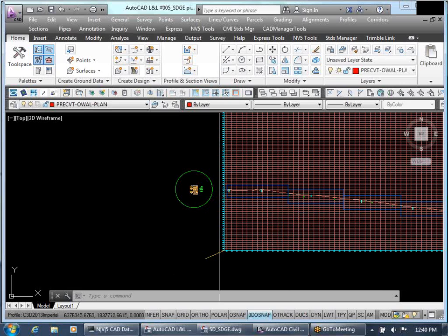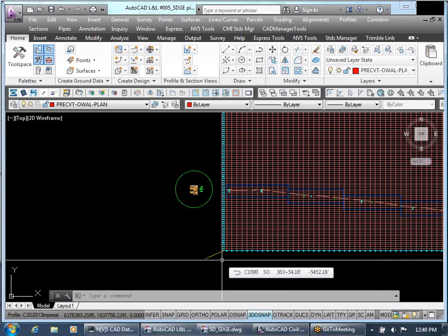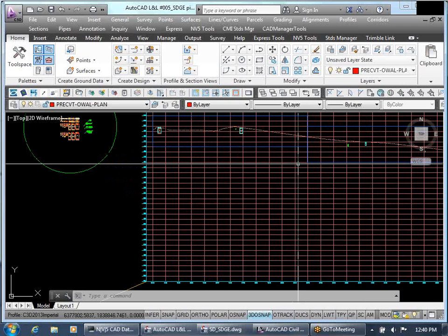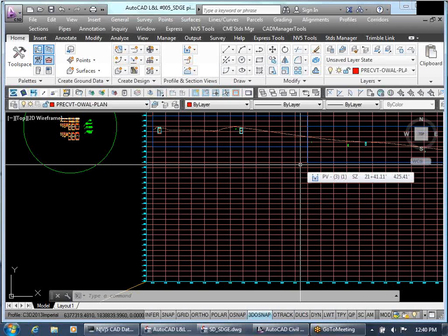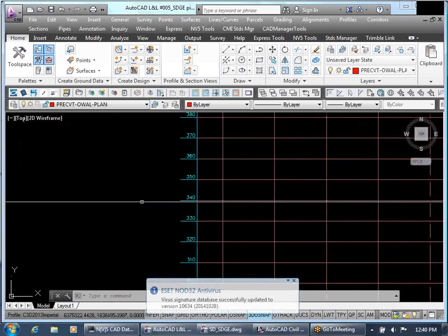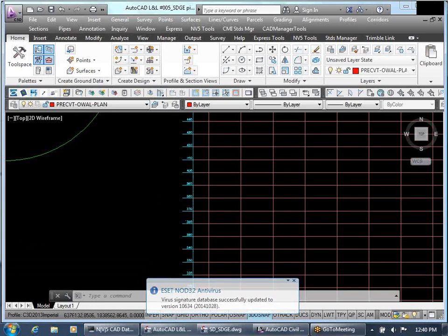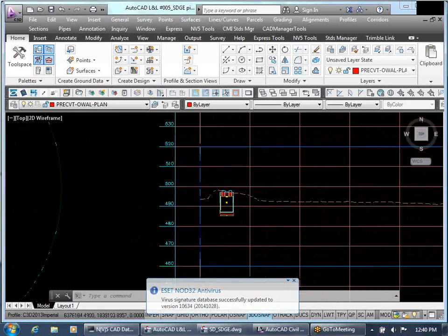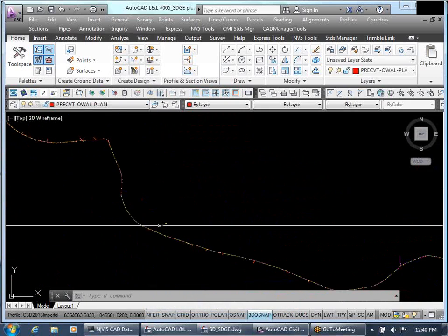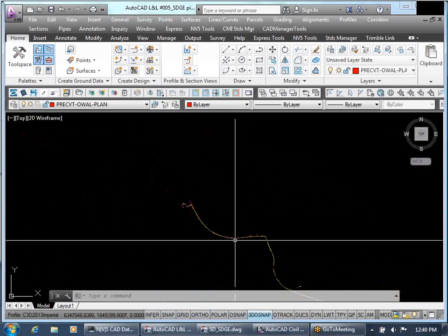So, like all things in Civil 3D, there's 3 different ways to do it. For me, this way is easier because it lets me verify that it's coming in where I want. If I'm dealing with one pipe, I would do it this way because I would then expect to see that pipe show up at 1850. Reason why I didn't is because our profile grid is in the 300s, 500s even, and I just randomly chose 2 points to draw a pipe.